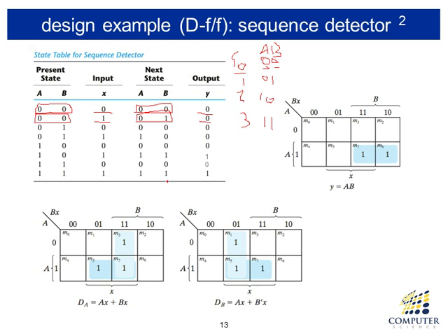Those states are stored in flip-flops. So what this table means is that, for flip-flop A, currently you have a 0, and on the next clock tick flip-flop A will have a 0 value. Currently 0, and it will have a 0 value. That's the meaning of a next state.